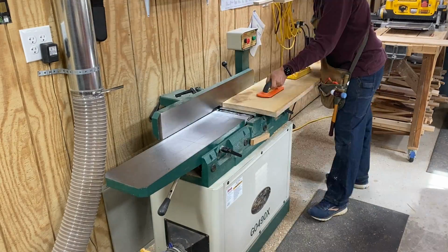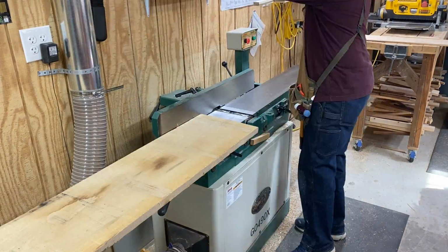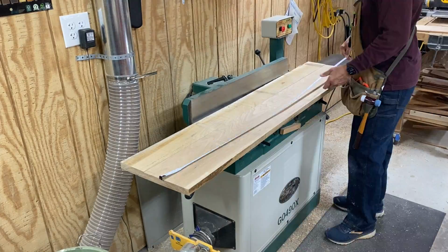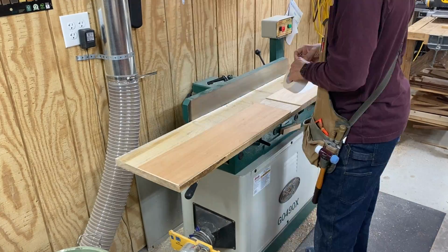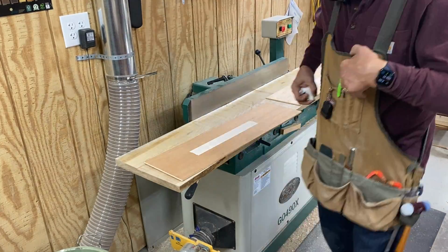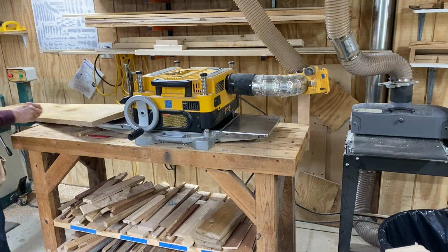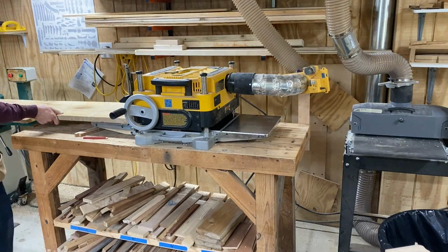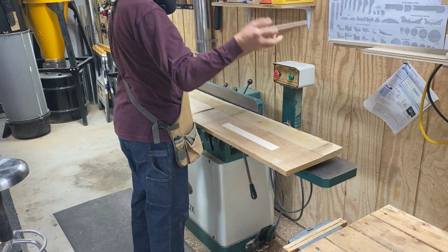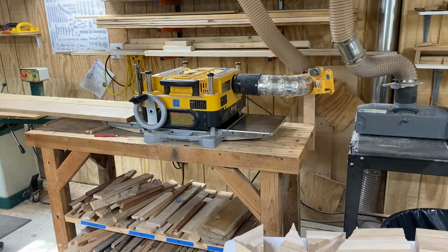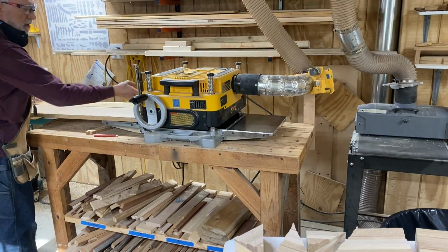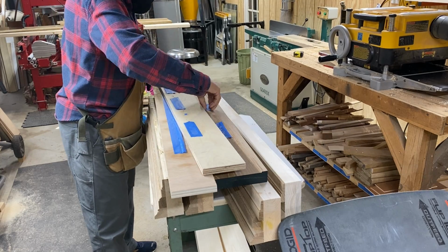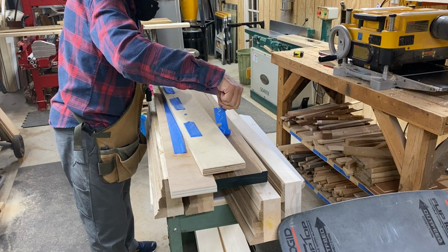Another scenario is jointing boards that are too wide for your jointer. By taking off the guard and using the full width of your cutter head, you can then attach a spoil board to the same side where it was flattened, and then plane the other side. You can then flip the board over after removing the spoil board and plane the remainder of the original side. I have to say I do not like the CA glue and blue tape trick. I tried it and glued the boards together because it's too hard to line up the tapes.